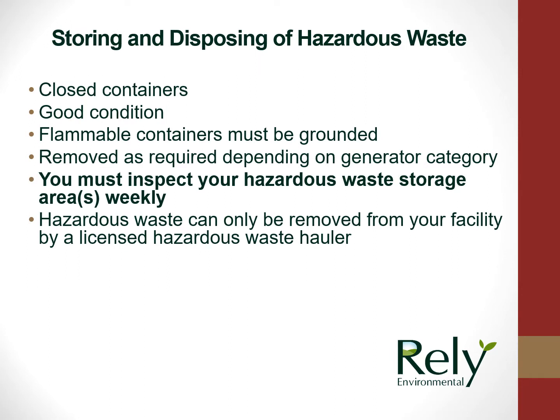Hazardous waste must be stored appropriately. Storage standards include closed containers that are in good condition, flammable containers must be grounded, containers must be removed as required depending on generator category. You must inspect your hazardous waste storage area or areas weekly.